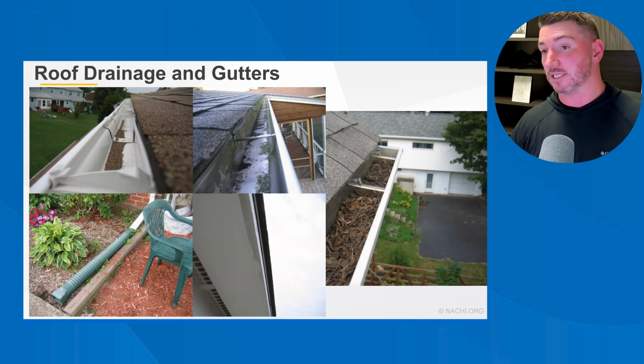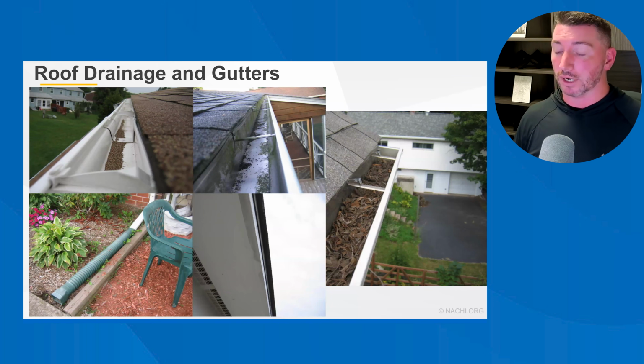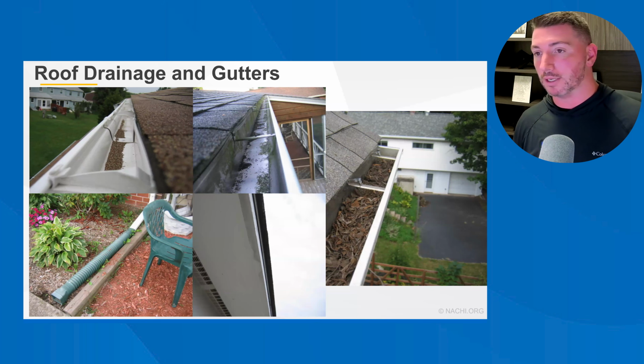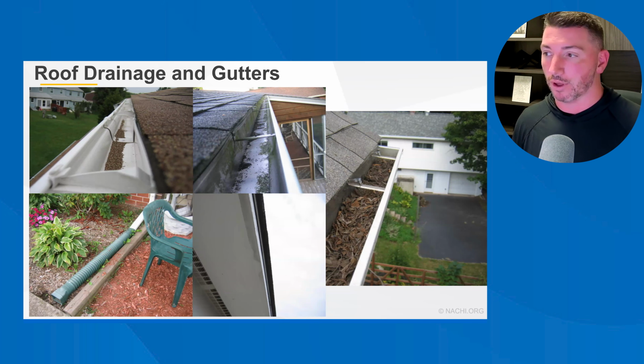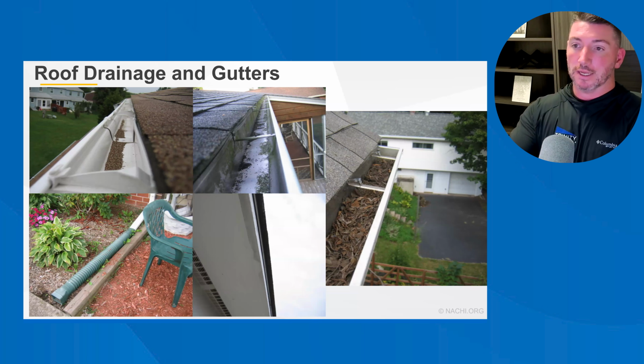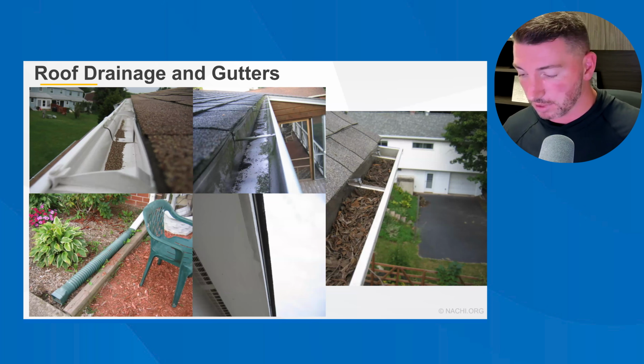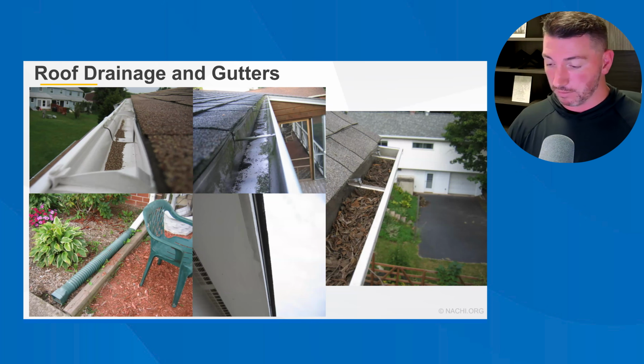So again, it's not just a conservative thing, and it's not just aesthetic to have it pitched only a quarter inch for every 10 feet. It's a matter of you want it pitched so that the water runs down naturally because of gravity, but you don't want a roller coaster with all that water piling onto an end cap where it's supposed to be fitting into a 3-inch hole, a 4-inch hole. It's going to spill over the end cap of the gutters.